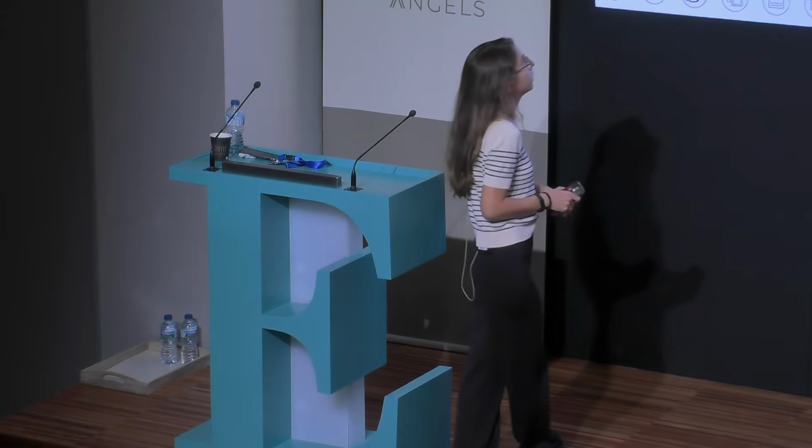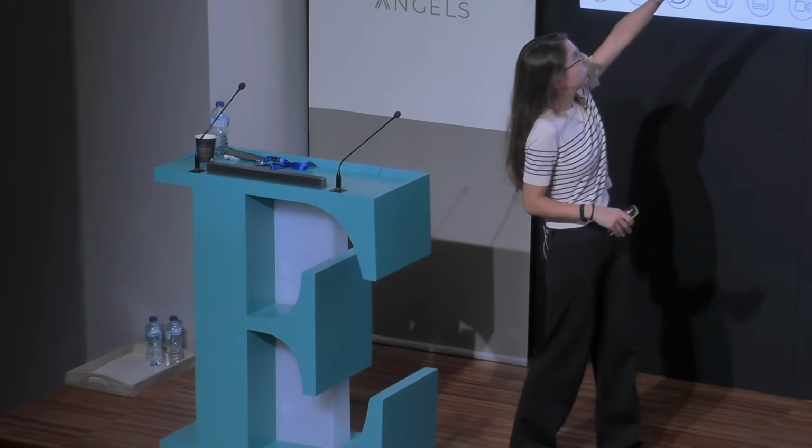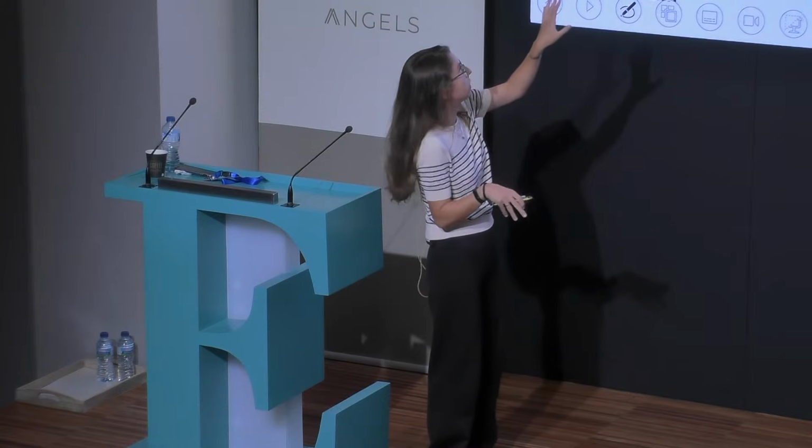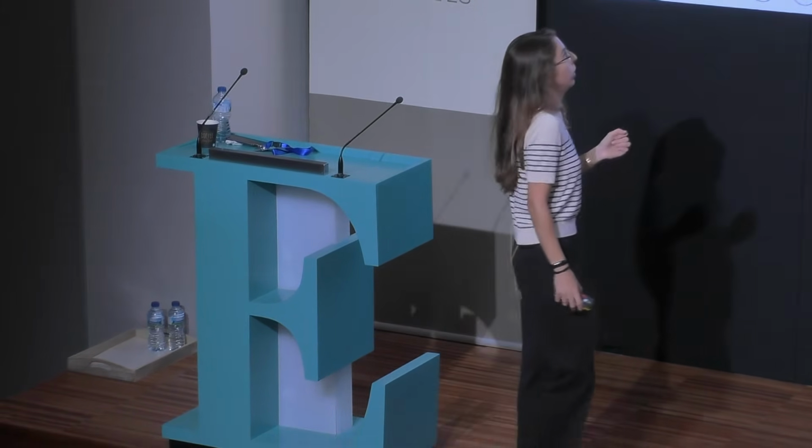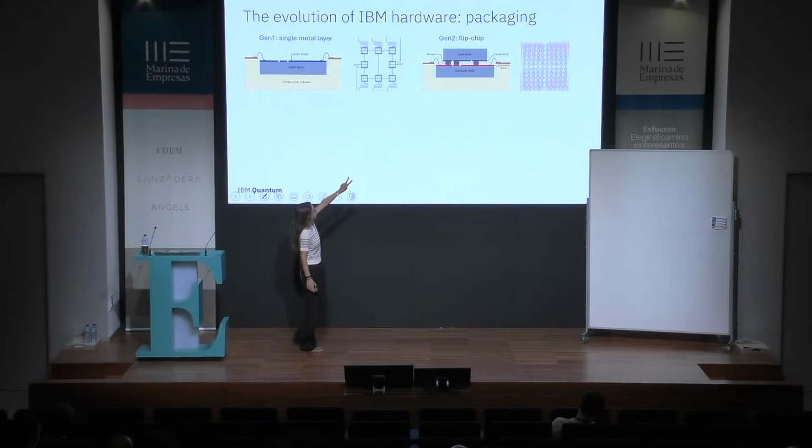This actually works quite reliably, and one of the issues is that it limits your topology to a ring topology. So you end up having to have your wiring, readout resonators and any other elements going towards the outside world, because things cannot cross each other. So unfortunately, we don't want to build our quantum computers as rings, and that's why a first step was to move to generation 2, which is this flip chip technology, where now instead of one wafer, you have two. The qubit wafer and the interposer wafer, and these are connected to each other via superconducting bumps.